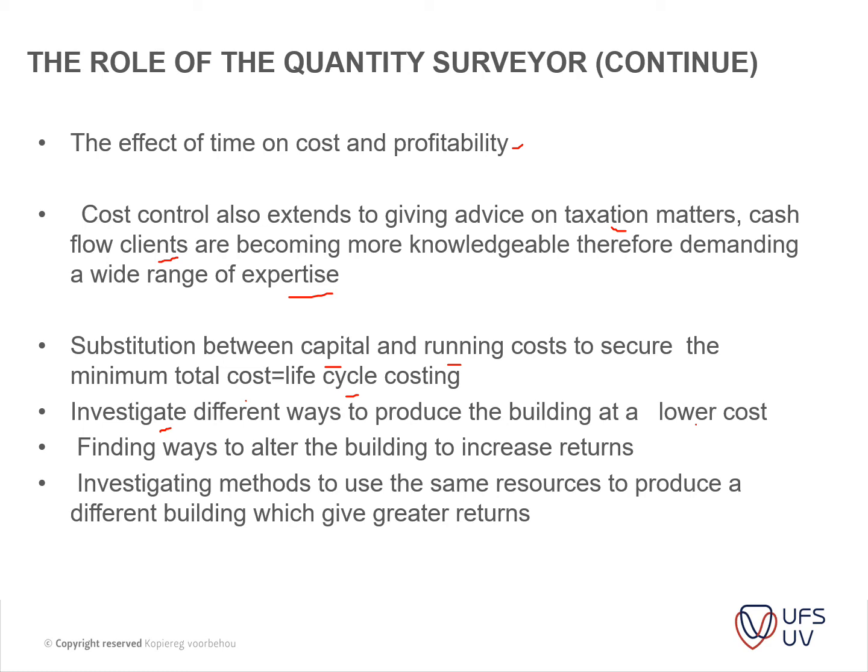For instance, if you look at solar installations, looking at the contrast between gel or deep cycle batteries against lithium-ion batteries. Lithium-ion batteries cost a lot more, but their lifespan is much longer. So then you can advise the client on the offset of the two.